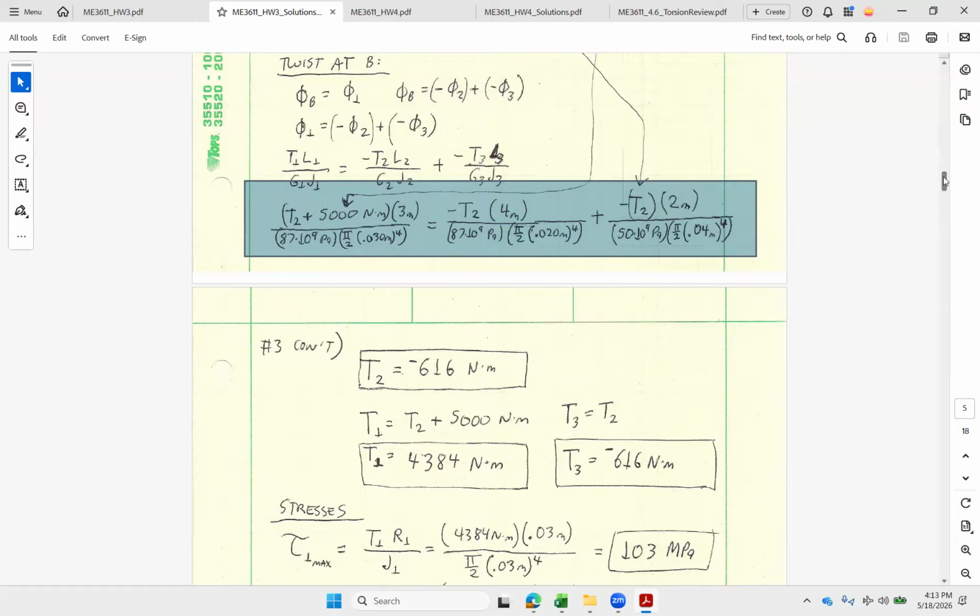And then 2 and 3 together are carrying the same load end to end, and it's a much smaller load, 616. There's a much longer length, and remember for our stiffness, GJ over L. So the longer we make the bar, the easier it is to twist it a given amount. We've got a short, stubbier bar for number 1, so it's going to carry most of the torque, and then together those two make a pretty long bar for 2 and 3 where there's no intermediate load, so they're not going to carry as much of that.